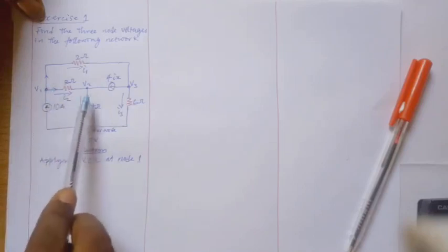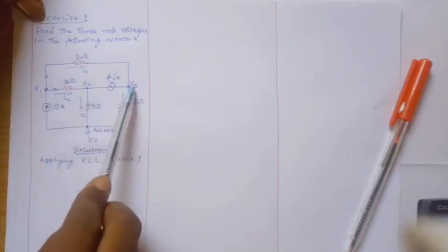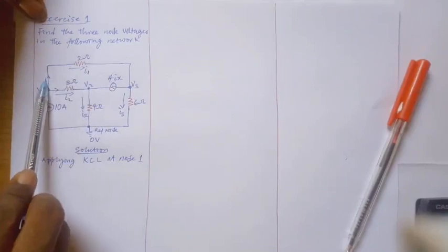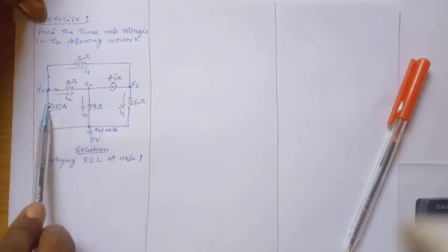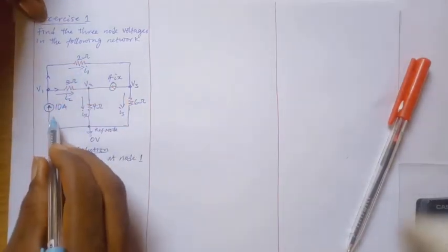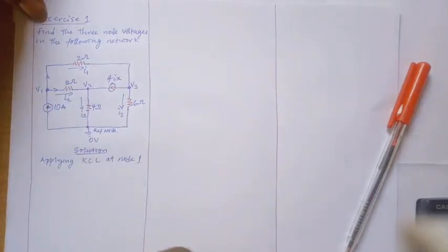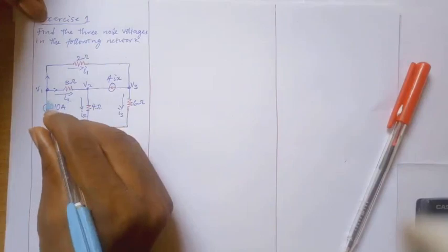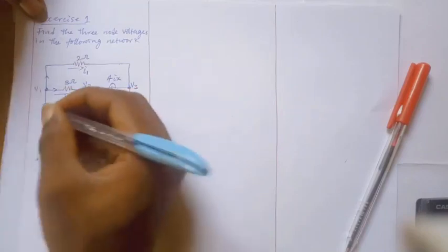So that means we are going to disconnect all this one and this one. So when we disconnect this one and this one, it will remain this, and this. Do you get that? It will remain this I1, I2, and this 10 ampere. Okay. Now, let's say this 10 ampere is already fixed there. You can give it anything, so you'll be able to understand it. This 10 ampere is entering. The arrow is up. It is entering the node.